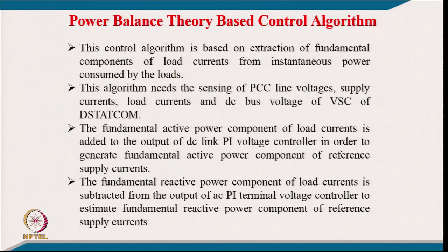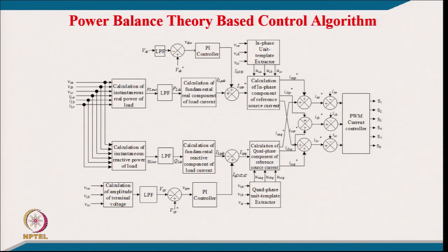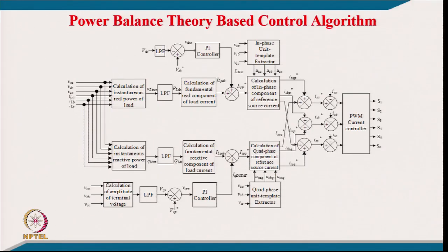So, what I mean here is we are getting the load active and reactive power, and we are taking that into control, because the load is consuming a major amount of active power, and the compensator hardly has 2-3% losses. So, this control algorithm certainly will reduce the burden on both PI controllers, for voltage regulation as well as for power factor correction.